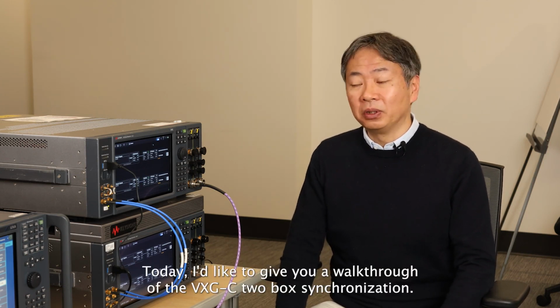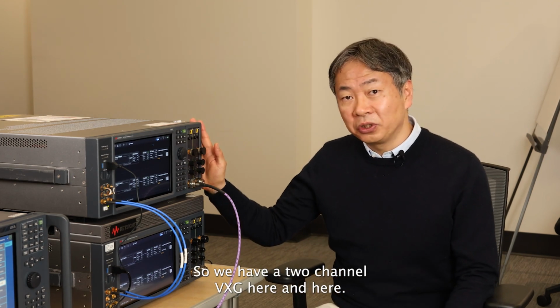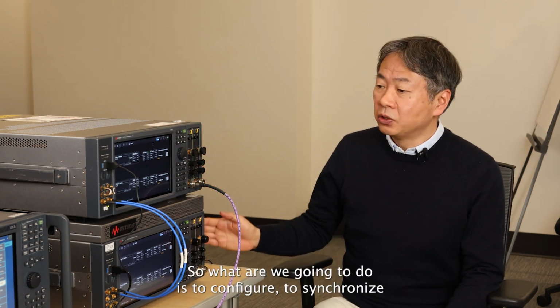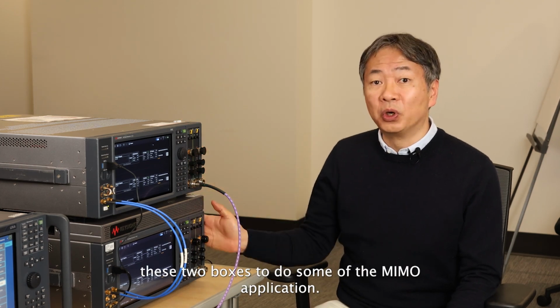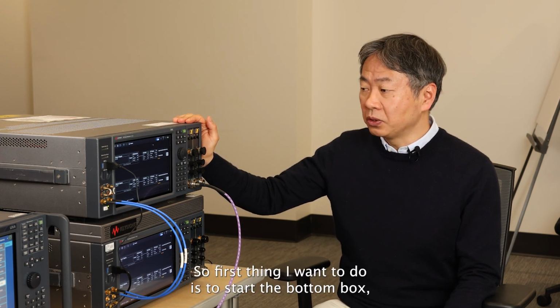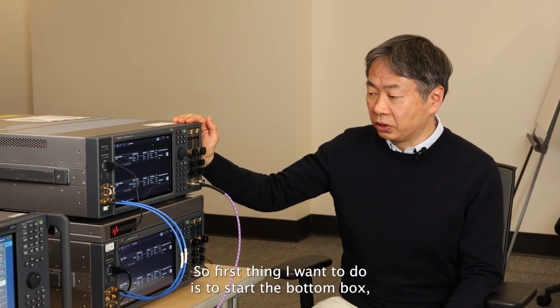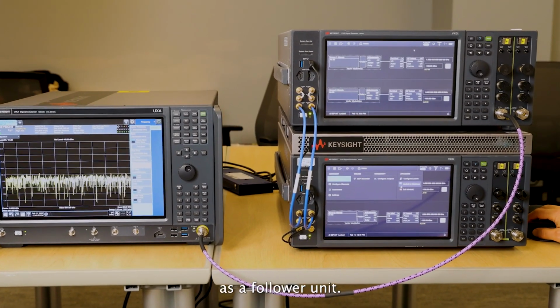Today, I'd like to give you a walkthrough of the VXG two-box synchronization. So we have a two-channel VXG here and here. What we're going to do is configure these two boxes to synchronize to do some MIMO application. First thing I want to do is start the bottom box as a follower unit.